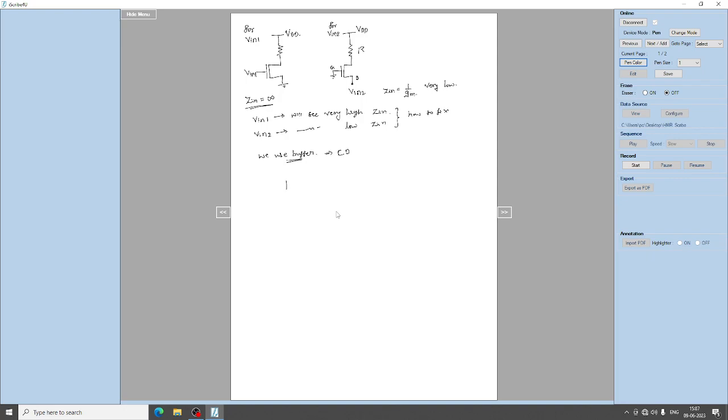So we can modify this common source amplifier; this is an NMOS transistor, with differential input, V in 1 given to the source terminal, and V in 2 given through a buffer, which has unity gain, and its output is given to the source terminal for the common source, V in 2 buff.